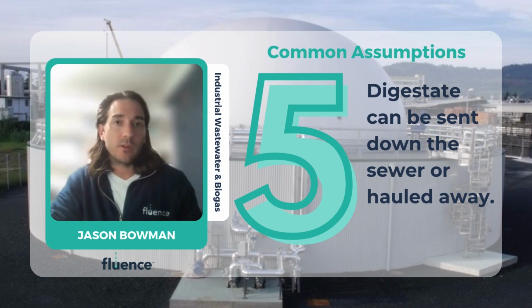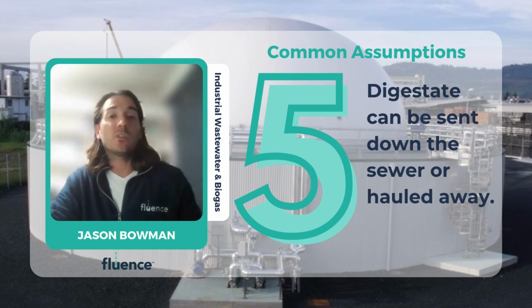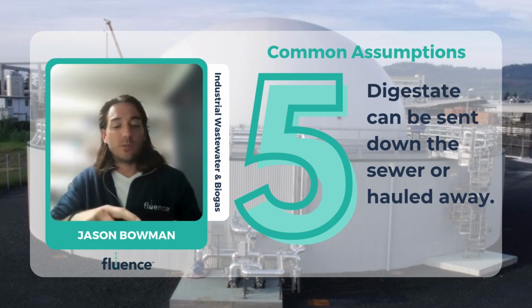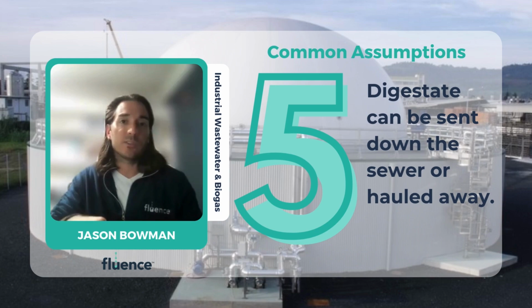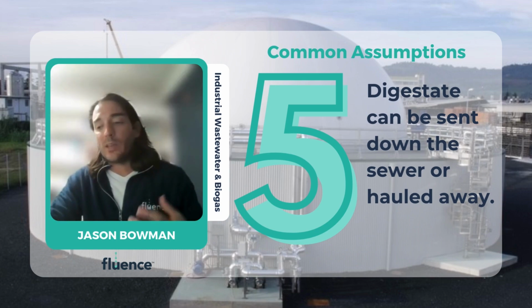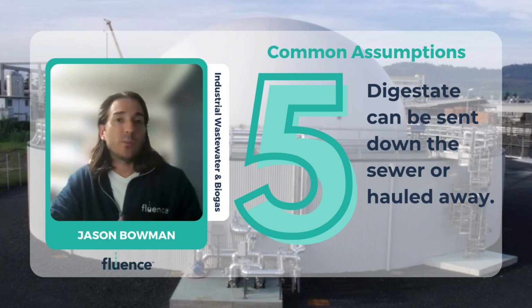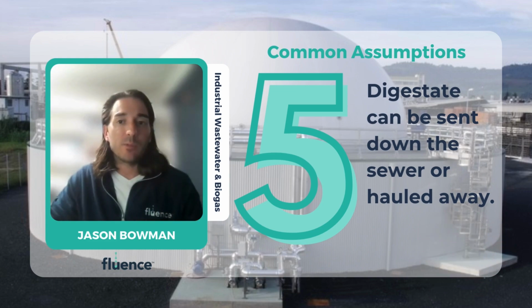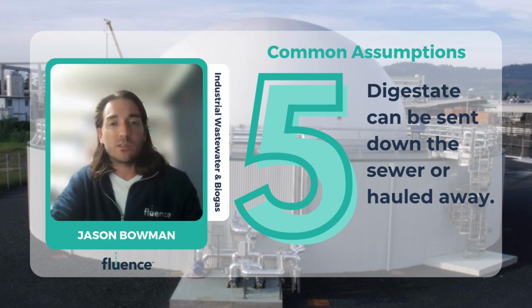So the last perspective here is, let's assume that the municipality did agree to take your waste untreated, but the agreement is there's going to be a surcharge. So typically municipalities surcharge based on flow, BOD, COD, TSS, TKN, phosphorus, and maybe a few other things. So by the time you add all of this up and you equate it on a per gallon basis, you could be paying anywhere from 10 cents to 20 cents per gallon of digestate discharged to the municipality. So again, on an annual basis, you're talking about millions of dollars. So based on these economic examples, it is almost always more cost effective and more holistic to build a digestate treatment process on site.